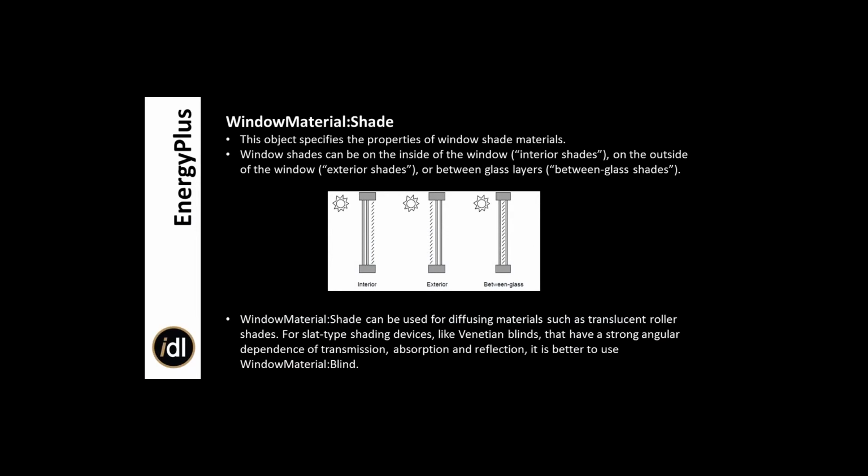So in EnergyPlus, before we export our file into EnergyPlus, we set all the things, the schedules, construction, loads, everything in OpenStudio. And just for adding the blinds, we export the IDF file and go to the text mode, and then use the window material shade for our model.